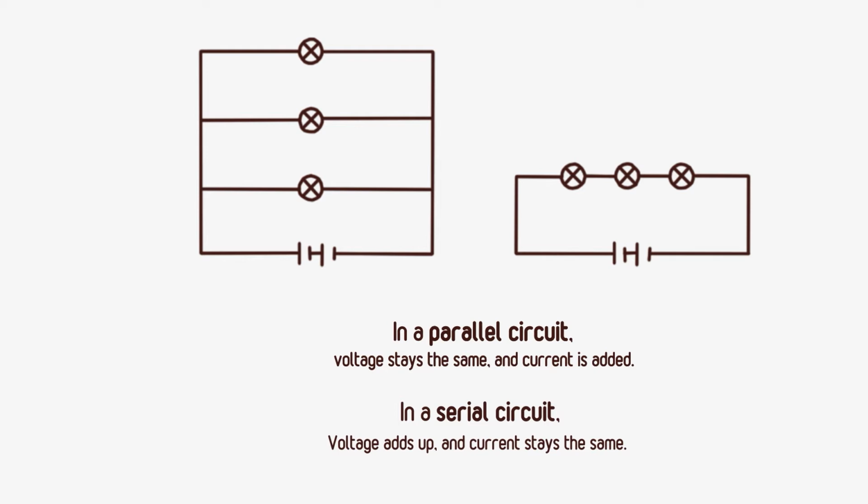So in a parallel connection, this is the example of a parallel connection. What happens is you have your positives and negatives all being connected together in parallel and then coming together to a single area, right? When you put solar panels in parallel, the voltage stays the same, but you increase the current. So you basically increase your pipeline, but you keep the force of that electricity the same.